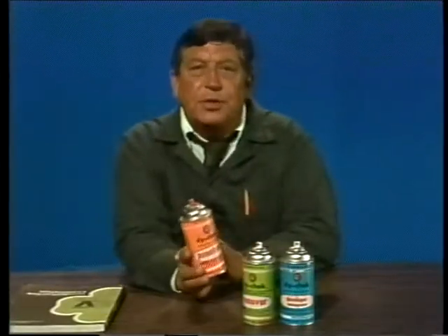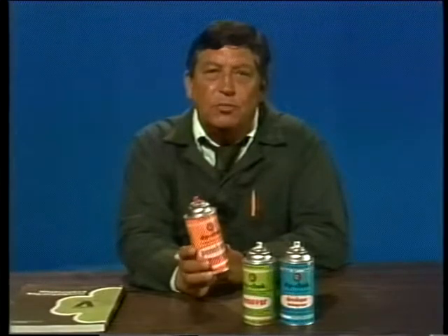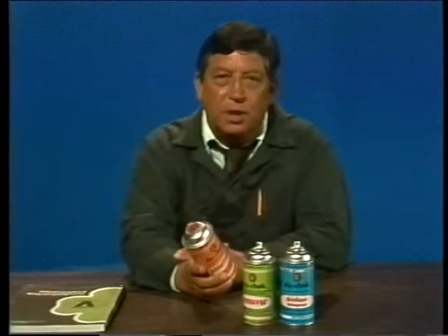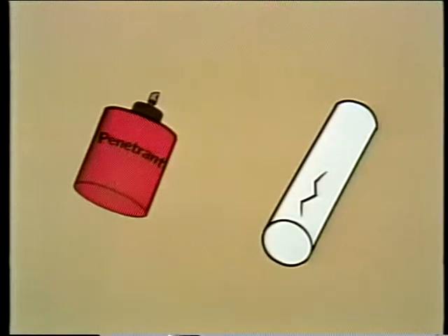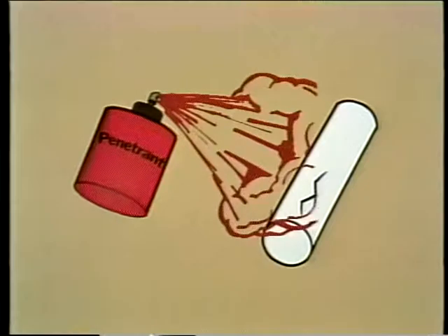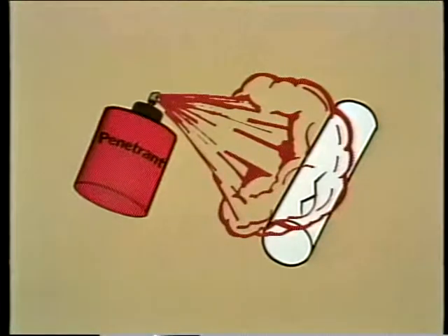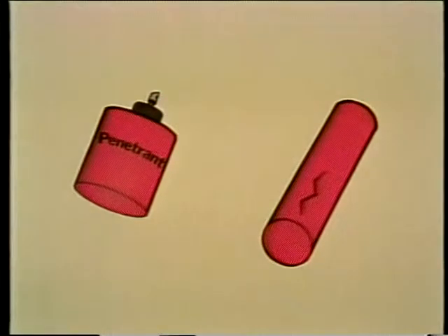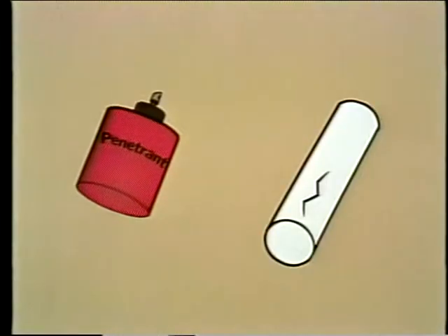Liquid penetrant testing is one of the most common types of direct, non-destructive testing. You'll be doing it yourself occasionally. This method, also called dye penetrant, uses a visible or fluorescent dye mixed with a light oil to penetrate surface cracks. After allowing time for the penetrant to soak in, a period of time called the dwell time, the excess dye is removed from the surface of the part with a lint-free wiper dampened with a solvent.